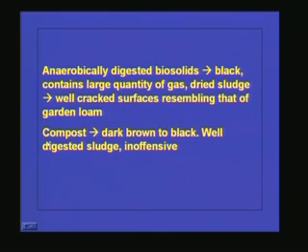Now coming to compost, because compost is a method to treat the biosolids. After composting also we will be getting some solids left over. The solids we get from composting are dark brown to black in color, well digested and inoffensive, and we can use them as manure or soil conditioners.